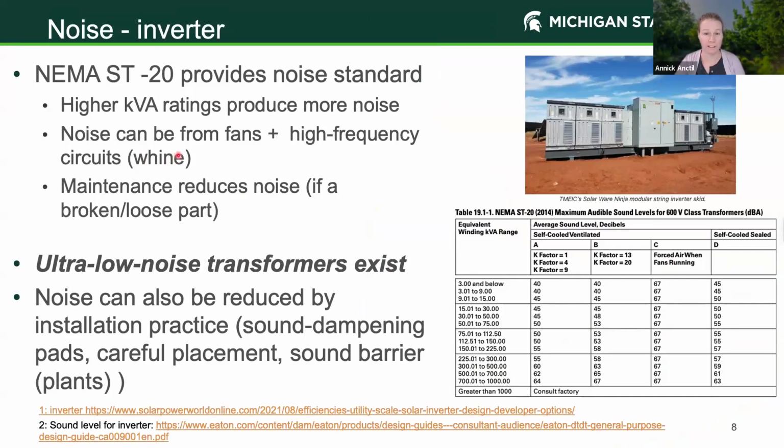It's kind of a low frequency whining, high frequency whining. And the bigger the inverter, the more noise it could produce. There are standards about how much noise an inverter should be producing. I've put the table there. That's the NEMA ST20 standard. So the maximum should be about 67 decibels. So it's not really low noise, but what is important to know is there are ultra low noise transformers that exist. So if that's a concern, if you're building a system close to houses, there are ways of choosing transformers that are better than others.